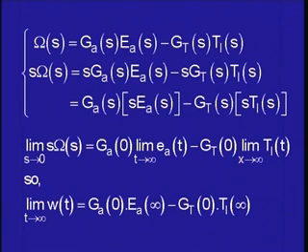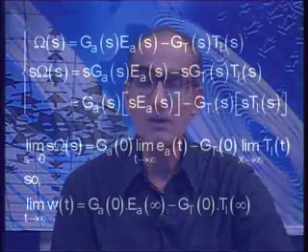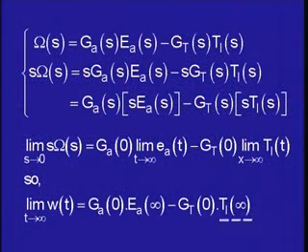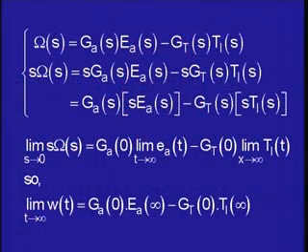Or if we are making no change here, let us say the applied voltage is just remaining constant throughout, then there is no change in the final value of the input from the earlier situation and the new situation, whereas the load torque has changed from one value to another. That change in load torque is what we will substitute here, and that will give us the change in the speed of the motor. So Ga0 and Gt0 are in some sense two numbers which determine the effect of change of applied voltage and change of load torque on the motor speed, or change in speed equal to Ga0 into change in voltage minus Gt0 into change in load torque.